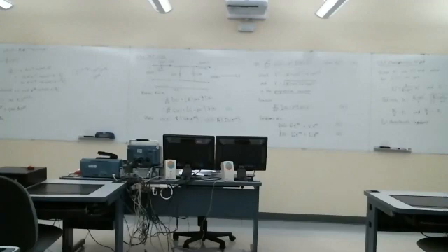Notice that this term is dominated by the j omega L term at this frequency. So this term is almost entirely imaginary, or the inductive impedance is much larger than the resistive impedance in this line. And again, this would actually be ohms per meter, because I'm not doing this over a distance of line yet. Notice the Z0 actually has the primed values in it. If you did it over a distance, all of these would be multiplied by the same distance and that would just cancel out.